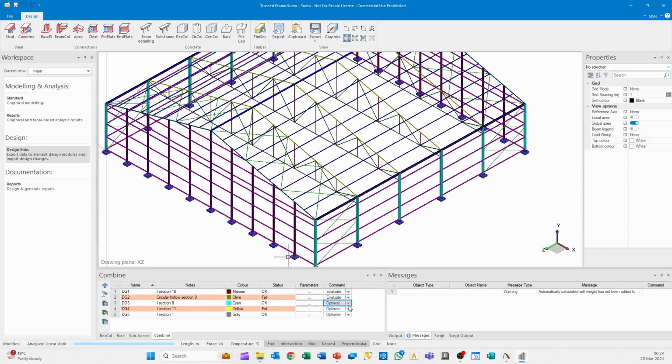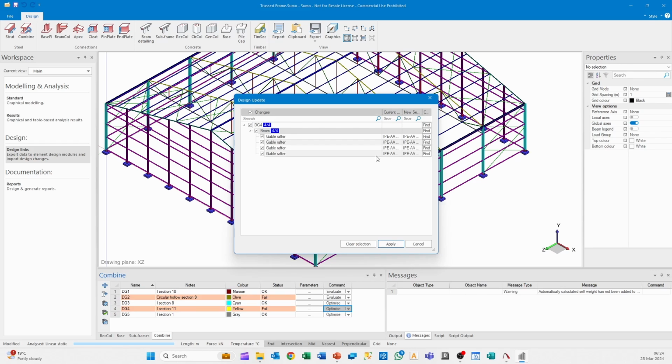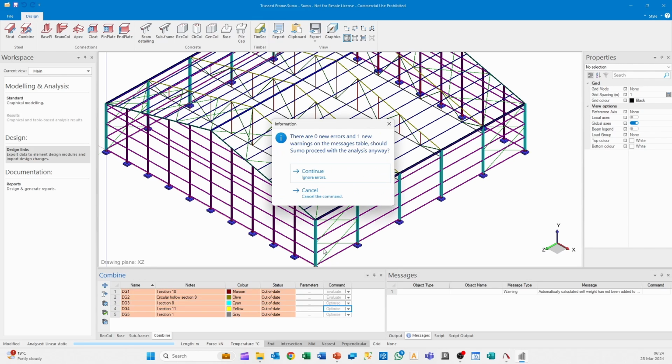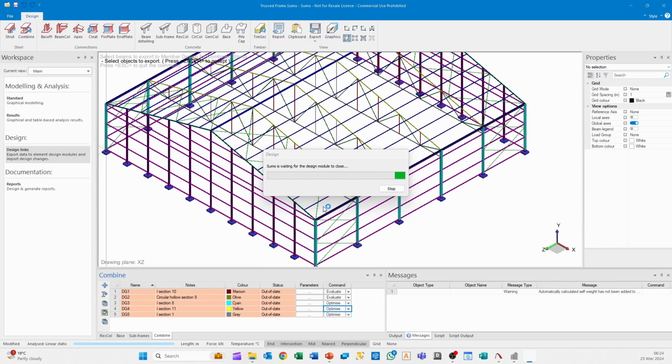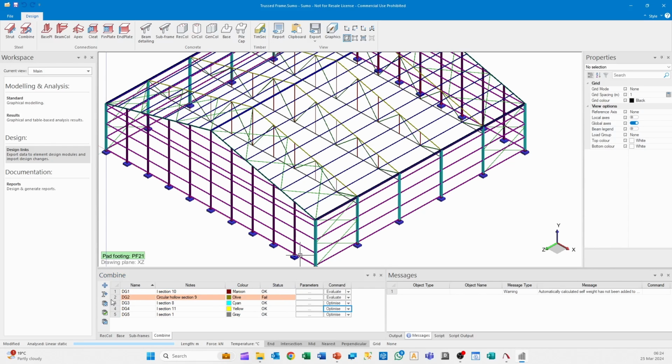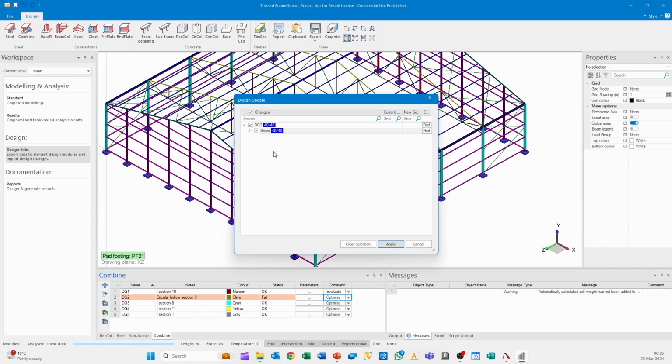Okay, that's great. So if I now optimize design group 4, see that there's a change, not a massive change. Evaluate all again. And the only design group left are the braces. And it might mean that those change because they are up there, that some of these design groups might fail now.